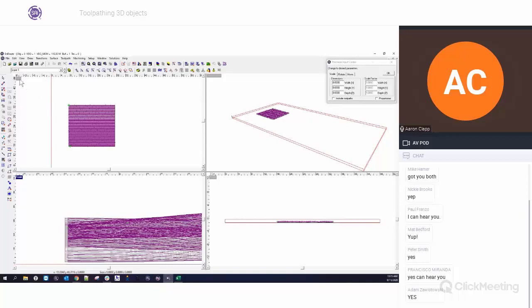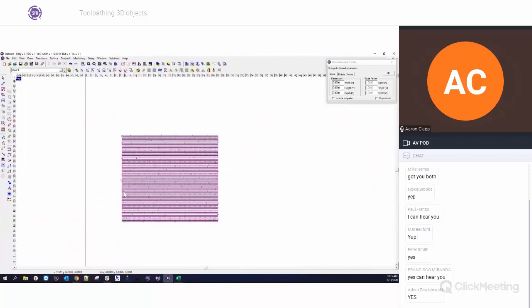Another way that you could take care of this is you could always run an end mill on the edge with a slightly smaller one. So if size is not that big of a deal, you could always run an end mill on the inside as an internal cut, and it would slice that off. That would be another way to take care of that, but I probably wouldn't. I would do it this way. This is a little bit easier because this gives you that nice, crisp, clean edge. So how about our next setting?